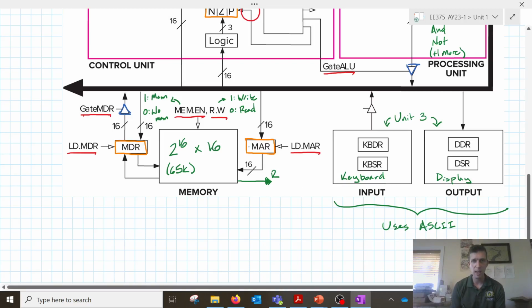You can see here I've got a memory address register, MAR, connected that gets data potentially from the processor bus and sets the address for memory. And whether or not this register loads a value is controlled by this signal here. On the other side of memory, I have MDR, my data register, that performs two functions alternately based on whether I'm reading or writing from memory.